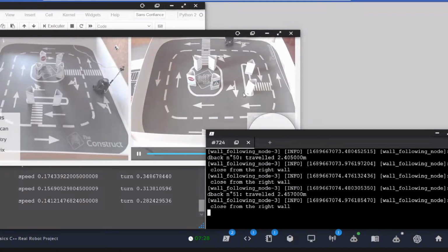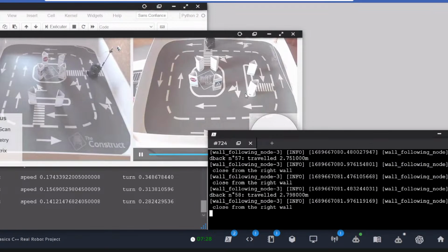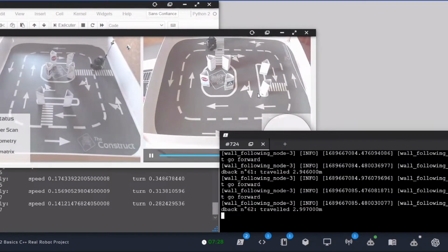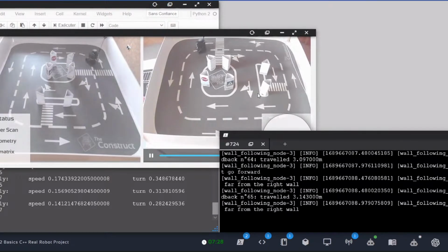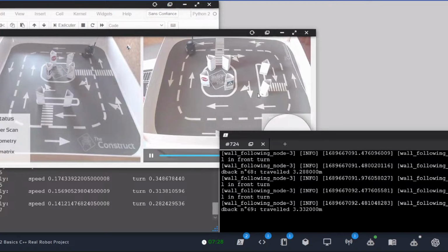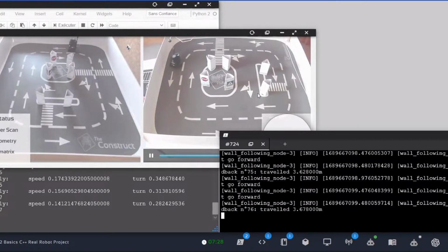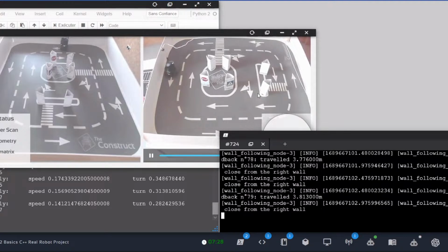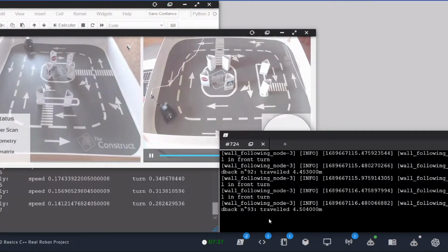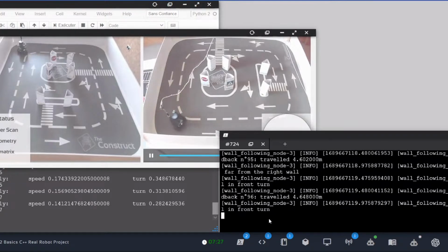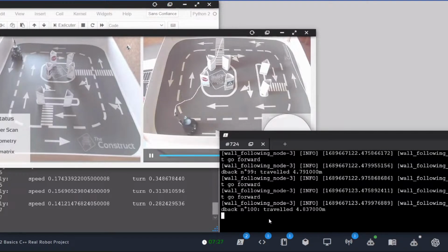Yes. Cool. And I also noticed something. Sorry, I'm going to be interrupting you, it's just to clear out some doubts. I noticed that it didn't go towards the obstacle, and it was closer to the obstacle in the beginning. Is there a certain algorithm you did to accomplish this? So when the robot comes too close to the wall, it's going to try to go farther. As you can see, it tells too close from the wall, from the right wall. So it's going to set an angular velocity to avoid the wall.